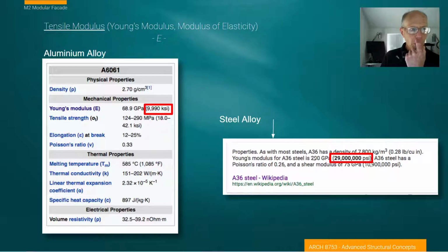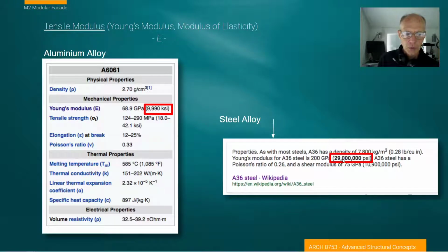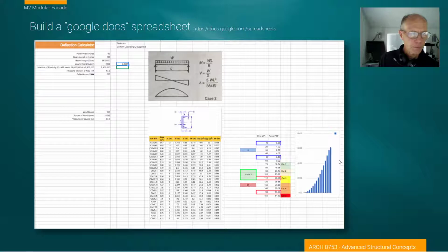We also need to know what kind of material we have because of the modulus of elasticity. Typically in these cassettes, we're making them out of aluminum because we're extruding these complex profiles, so we have the idea of probably using this value. But we could be using steel, especially if we had to do some kind of reinforcement, so I wanted to capture the value for steel also.